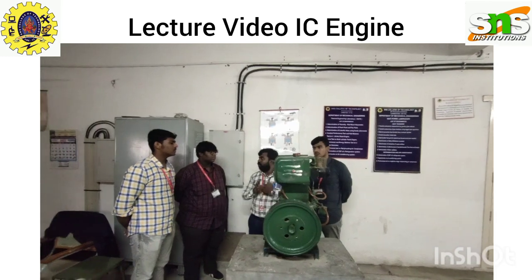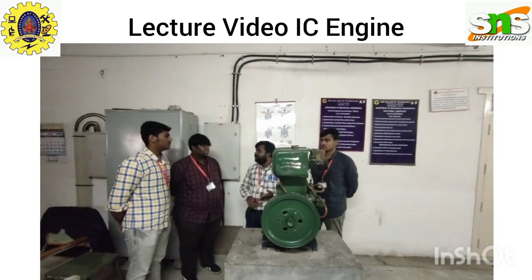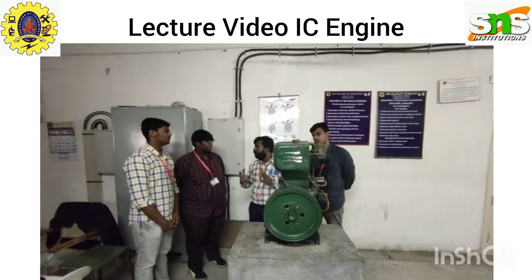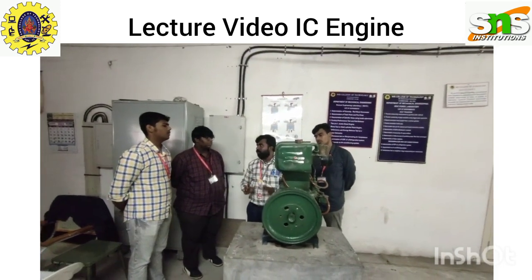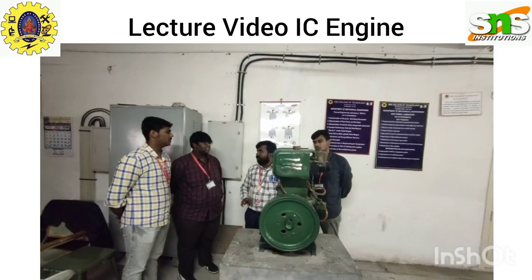In a 4-stroke engine there are 4 strokes: suction, compression, expansion, exhaust. So the complete 4 strokes give 1 power output. 2 revolutions of the crankshaft give 1 power output. This is the 4-stroke diesel engine working principle.